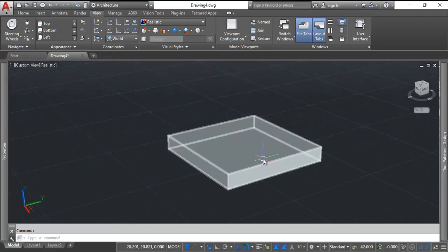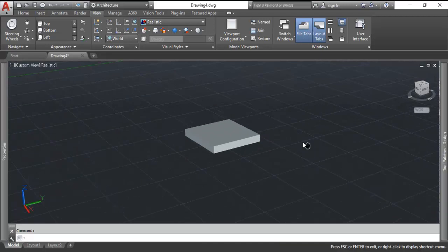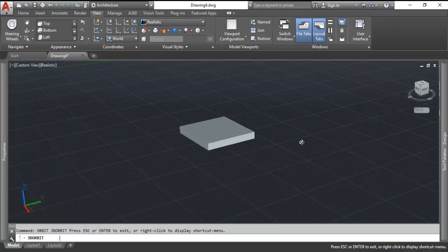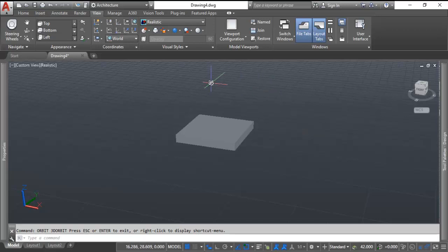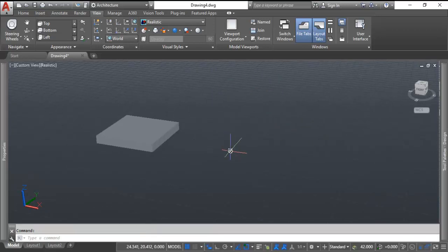Now next we have the side, and this is kind of an odd shape, so the easier way to do it is to draw a series of lines, make it a region, and extrude it. So I'm just going to pan, so I'm looking more at the left view, and I think what I'll do is change my UCS. If you see right now my UCS is laying flat.